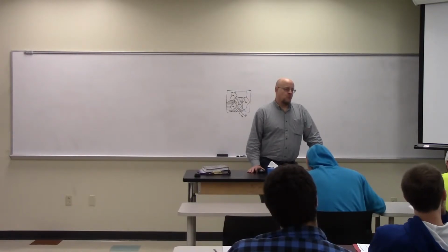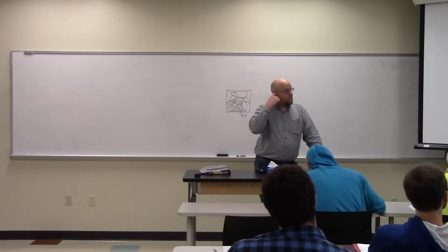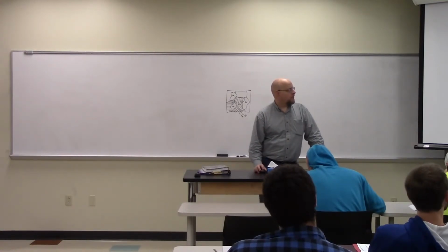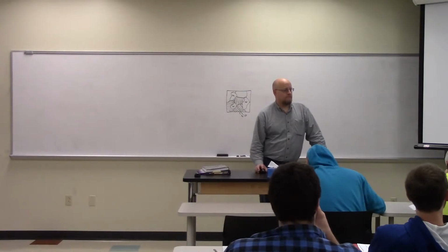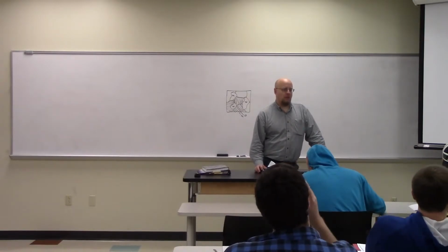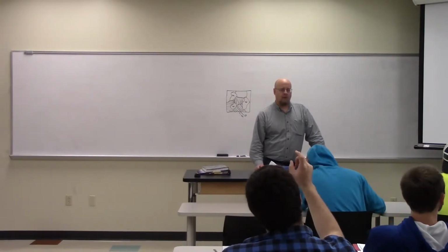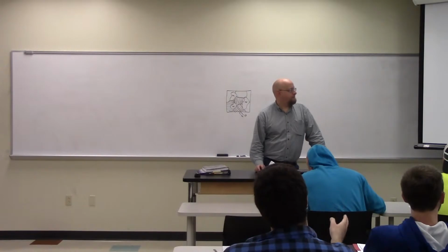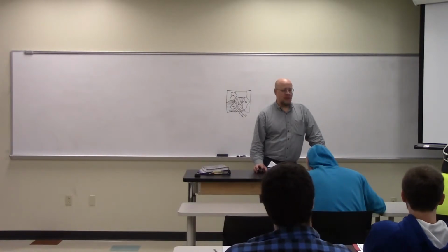So whenever you cool down so that you're passing the eutectic point and you're not in one of the solids, then you are going to get the lamellar stuff. If I'm anywhere between 19 and 97.5 on this diagram, I would get some lamellar structure. Yes. Right through the eutectic point, you get pure lamellar though. That's what he just asked.